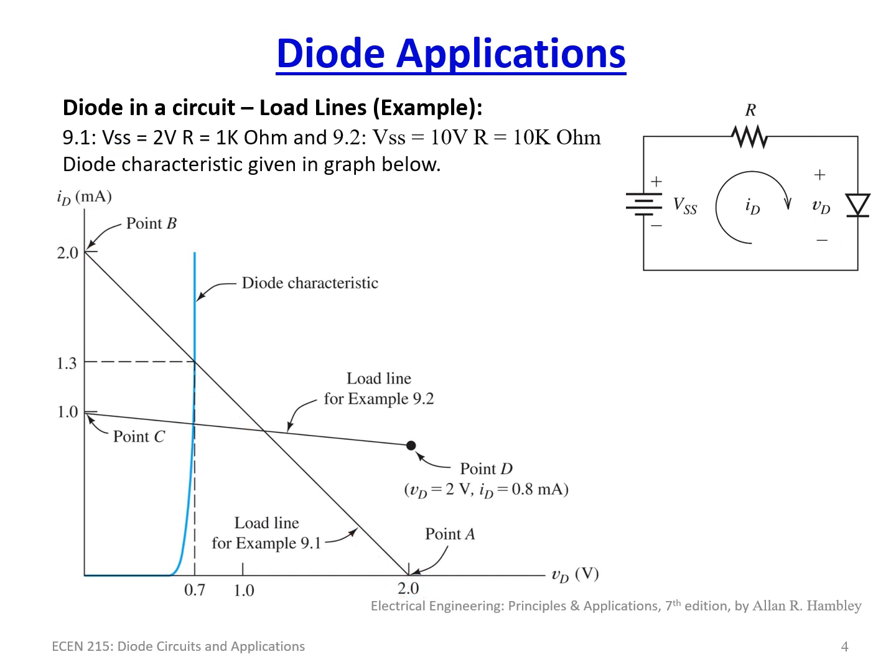And that's how we get this. What we do is then take our load characteristic for our diode, or the diode characteristic that we have here, and we look for that intersection. That intersection for this particular example is right here, which tells us that VD is going to be equal to 0.7 volts at an ID equal to 1.3 milliamps. So that's our load point right there.